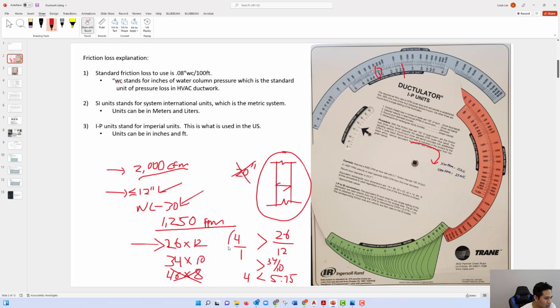And this is again just a general standard that our company uses. If we really need to use a ratio that's higher than this 4:1, we can do that, but we generally try to avoid that. And that means that these are the two available sizes that we can use for the ductwork that is carrying this 2000 CFM, with the maximum height being 12 inches.